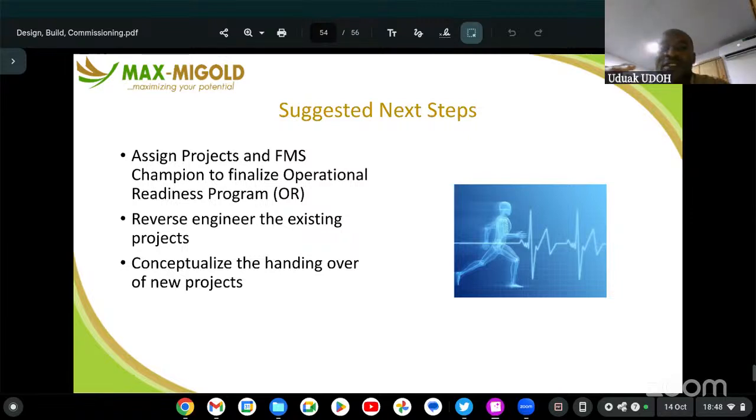For instance, now, I'll be quick about this. There are some systems you go into that the distribution boards are not labeled. So how would you know what each of those breakers serves? And that's why we work as a team. You put different guys in different locations, and at a convenient time, you start switching off each of the breakers. It's going to be tedious to really know where these breakers work. Then you label such breakers.